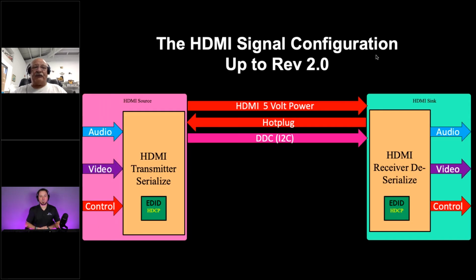So Analog Devices makes a chipset that does format conversion, and they have an I squared C input to it. Then we have a microcontroller in there that we program, and we talk to that input by way of I squared C. It's just a protocol. It's just a language. And when we say to it, go to S video, or go to RGB, or change your resolution, we can do that with all this data, and it's just all clockwork.